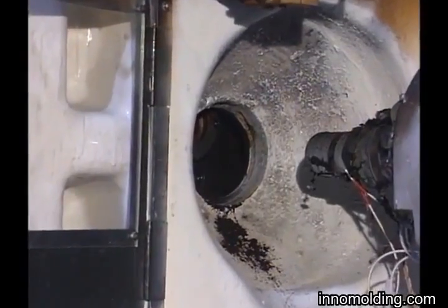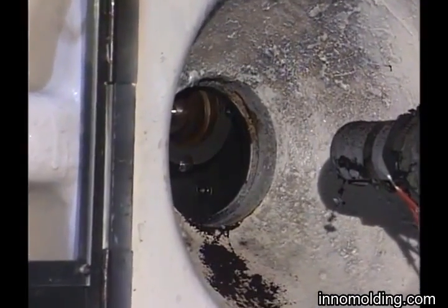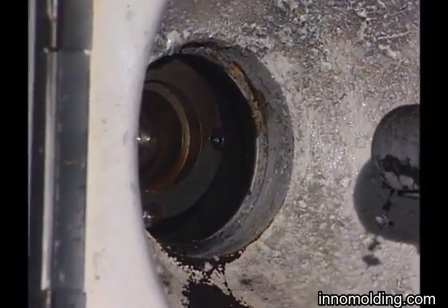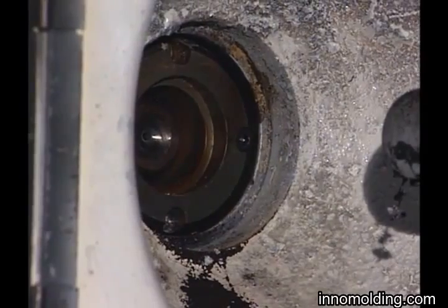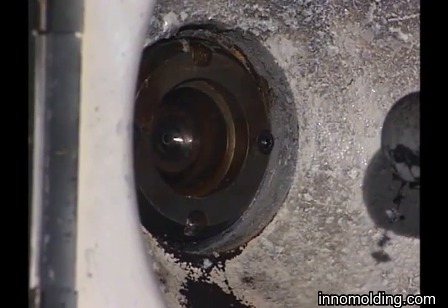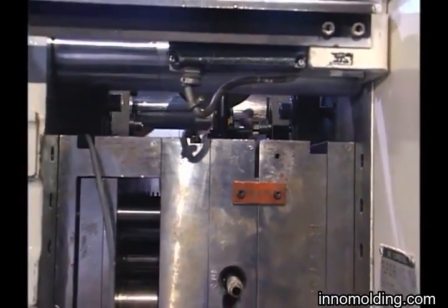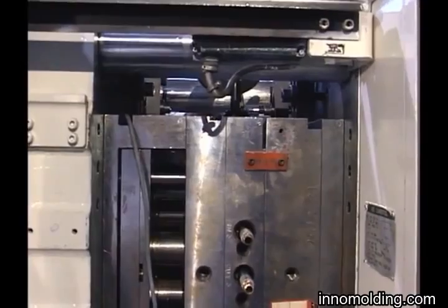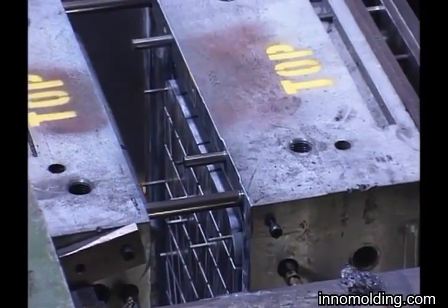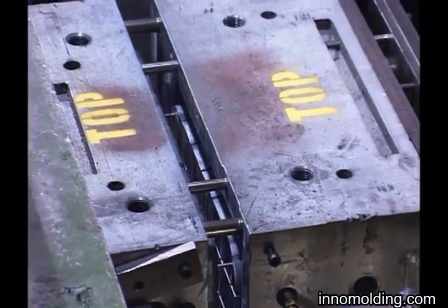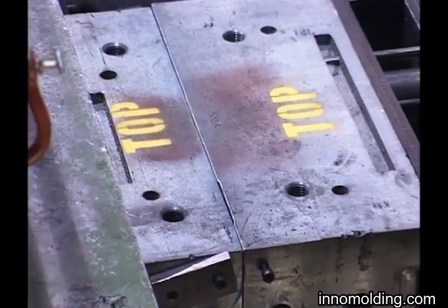As the injection mold is installed in a machine, a locating ring, which seats in a hole in the stationary platen, serves to locate and center the mold. The mold sides are secured by clamps which are screwed into tapped holes covering the platens. Leader pins and bushings align the mold. One pin is asymmetrical to prevent improper assembly.